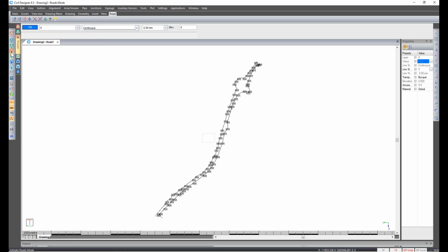Eventually I'm going to go to the roads mode. I'm going to go to signage, add linear road furniture, and in using this function you need to obtain a polyline, or alternatively you could design a road and then use the display line of the road. In our case we're going to use the polyline function. So pressing escape, we're going to use the draft expert.